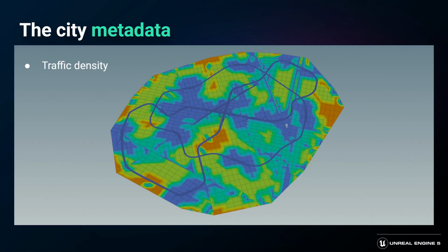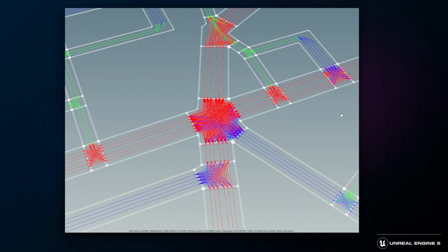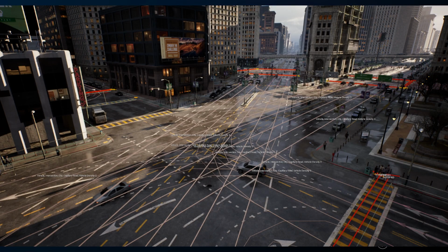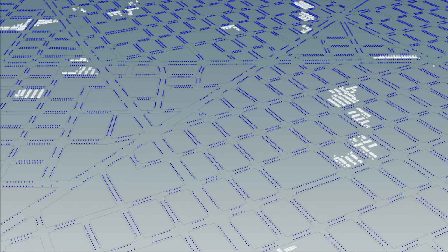For the traffic, we did the same thing. We merged the procedural data representing the traffic density, along with the traffic lane network, to create a traffic zone graph network, and then generated the spawning locations for the various vehicles. Note that for the traffic, we had to do that operation for both the city lanes and the freeway lanes, and then interconnect both networks. Finally, for the parked cars, we simply directly spawn one at every location fed by the point cloud.